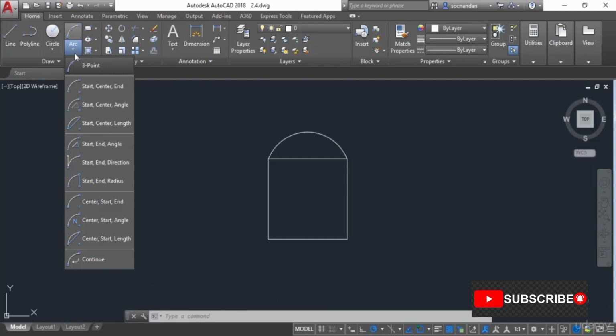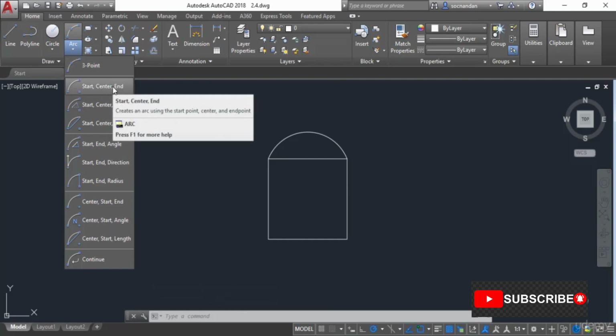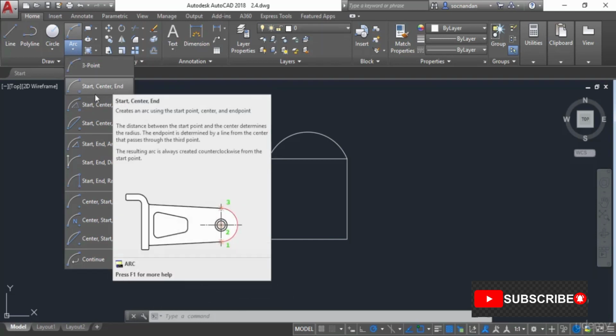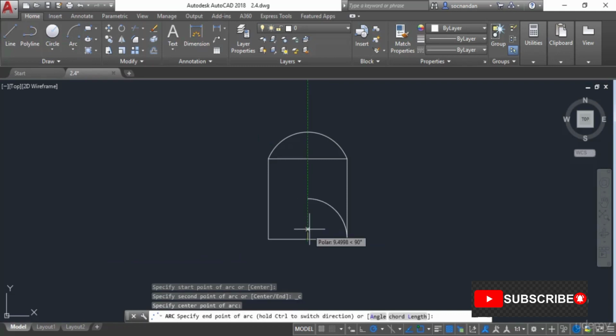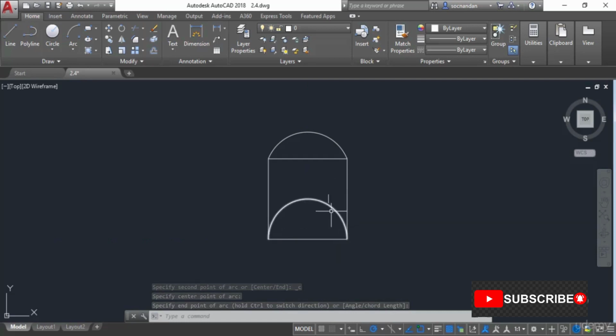Now let's look at the other option, which is start, center and end. So here we need to enter the start point at first, then the center point and the end point. So now let's start with the start point. So I'll click at this point, that will be the start point. Now I'll click at the center point, which will be the midpoint of this line. And now you'll notice that the arc is being formed in anti-clockwise direction, just like this. And now you only need to enter the third point. So click anywhere in the drawing area to apply the third point, and I can click here to make the arc. And here we have it.